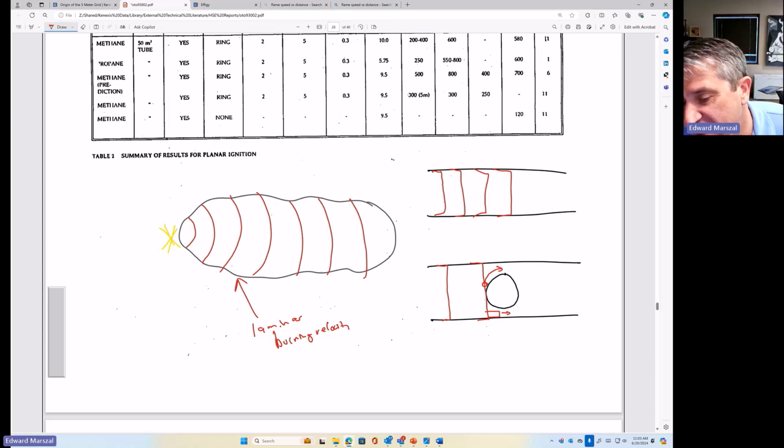So this introduces material that's going faster, and when that material that's going faster gets back to unobstructed, it doesn't really slow down, it just kind of changes direction. So we're going to get all this mixing, and that's where the turbulence comes from. And as you get more turbulence, the flame is going to go faster. So it might be kind of counterintuitive that putting something in the path of the flame front is going to make the flame go faster.